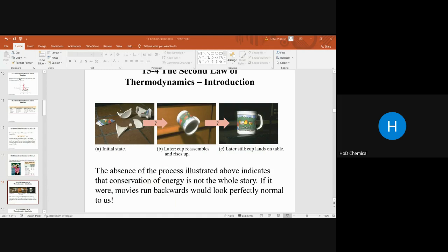For a closed system this is represented as dS greater than or equal to dQ divided by T. This is the basic general process, which may occur including work being done on the system, with frictional and various effects, because a chemical reaction may be in progress, or because the heat transfer occurs irreversibly, driven by a finite difference between the system temperature and the temperature of the surroundings.